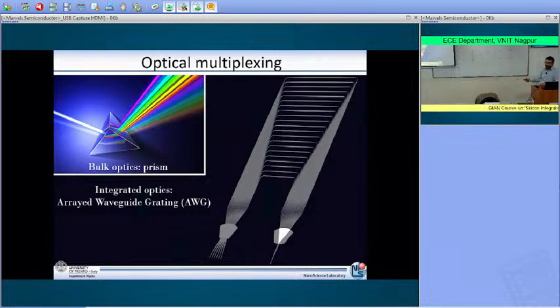So here you are increasing the length of each waveguide by a given length. This increase in length causes a different phase shift between the light traveling along all those different waveguides. Okay? And this difference in phase behaves like a grating. Therefore, this system behaves as a dispersion grating.